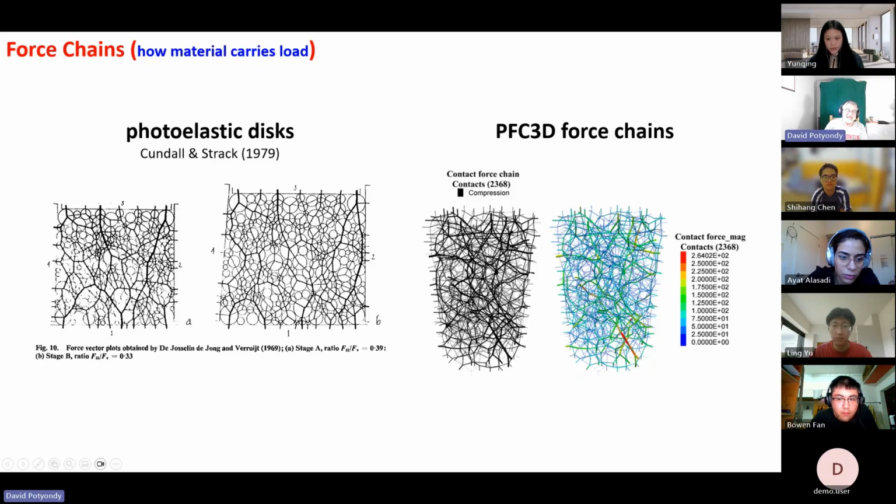And you actually can see these different colored lines. And these lines correspond with these force chains. Okay. This is a real system. This is really how granular materials behave. They carry load through force chains. Okay. And if you look at this carefully, there's the same thing. This guy here is not carrying any load. Right?